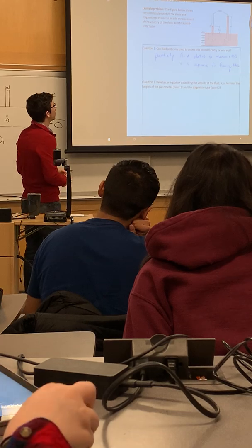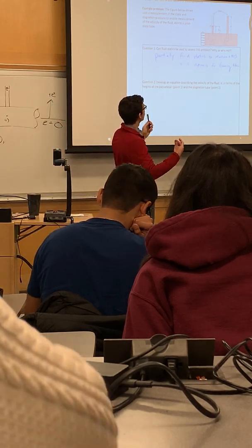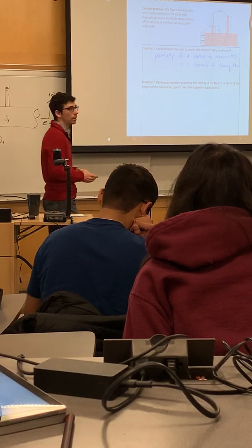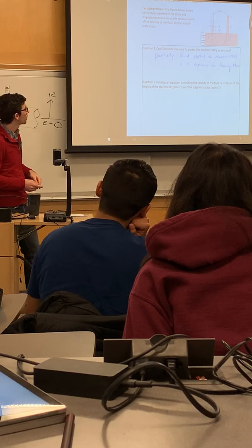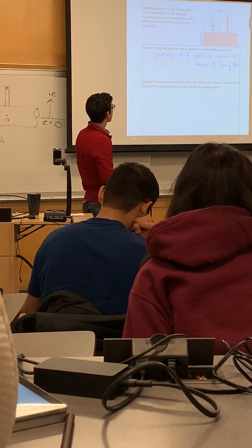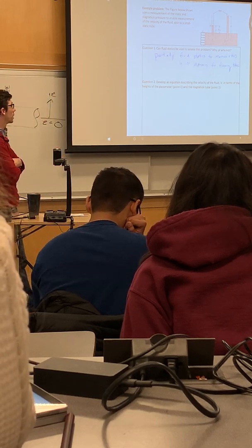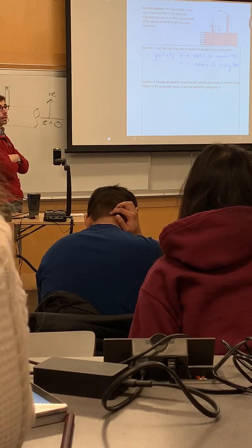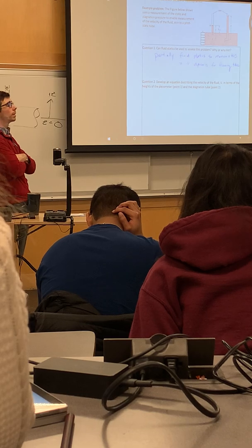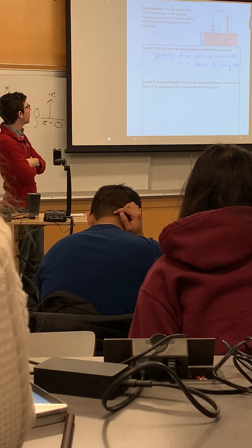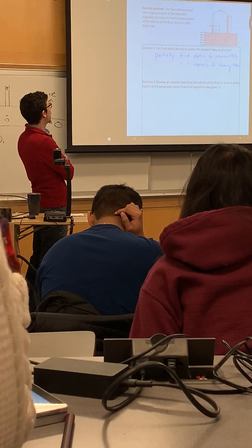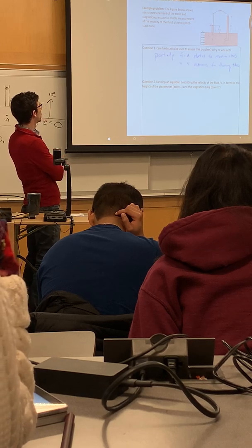And so at point 1, it tells us that at V1, the fluid has some velocity V, right? At point 2, where we dropped our second point for Bernoulli, we say that the velocity at point 2 is equal to 0, right? And this is the difference between a piezometer and a pitot tube, right?